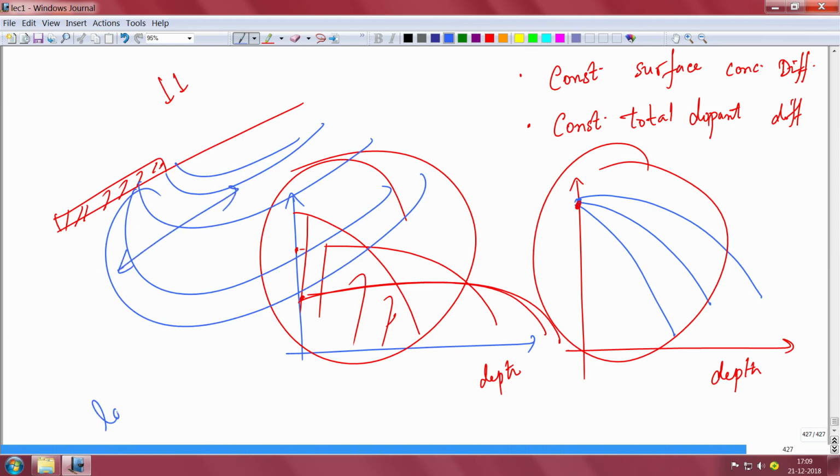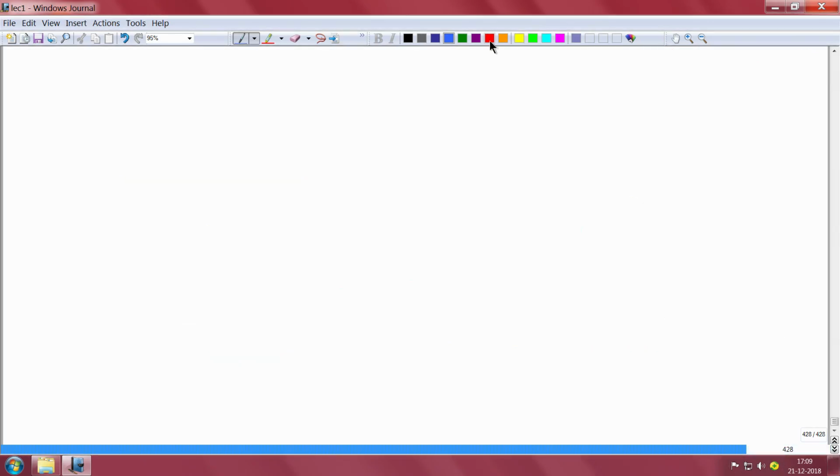There is a lateral spread of the diffused doping species, and it is isotropic. So it spreads everywhere in the wafer, in all the directions it can go. It is not like an anisotropic diffusion. That is why people nowadays have also resorted to ion implantation, which is the next topic. People still use diffusion, please do not get me wrong, because they can reach much higher depths. And then you have ion implantation.